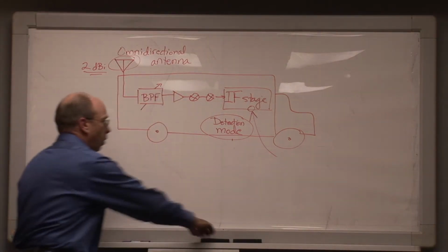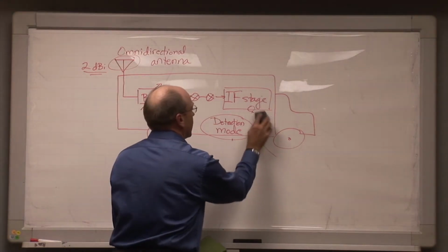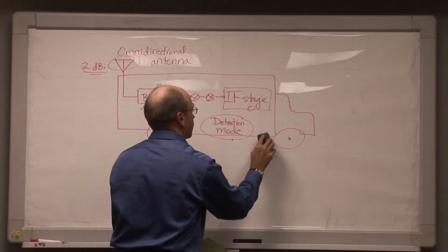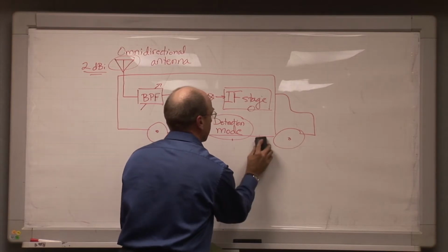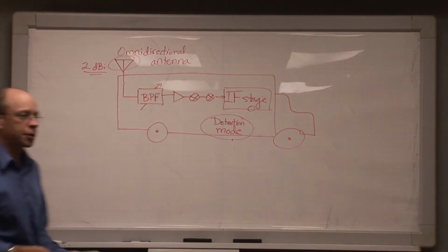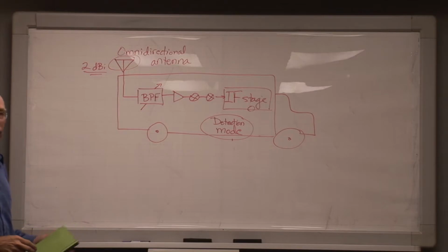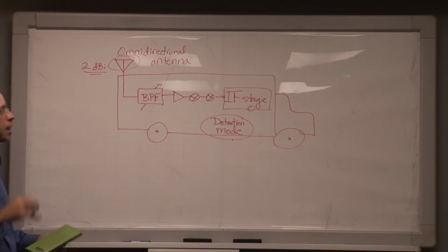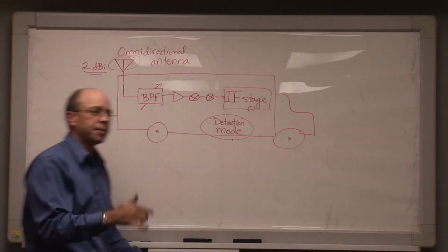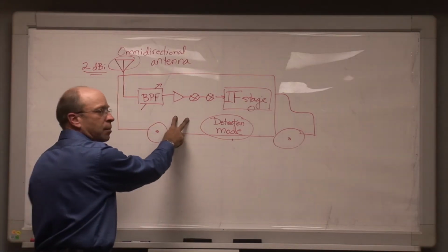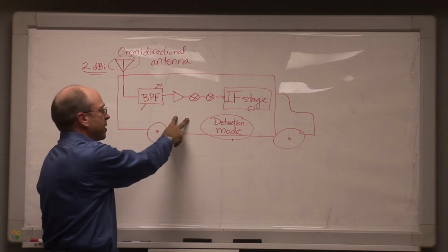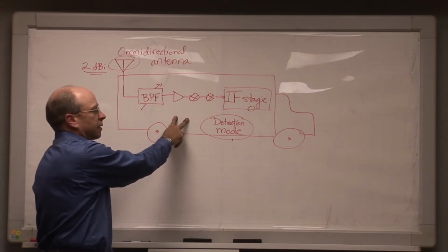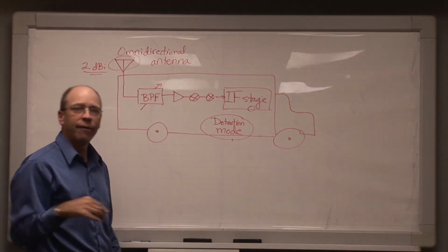We then coordinated with the agency that actually controlled that source that was involved in the interference production, and we said, can we come to a particular site where your aircraft are located and measure the spectrum of this source directly? And they said, sure, absolutely, so they let us. Sometimes the interference source may be a fixed source that's close to where the victim receiver is, in which case we only have to drive maybe a mile, or half a mile, or 1,000 yards to get over. Other times we might have to, as in the case in Florida, drive halfway across the country.